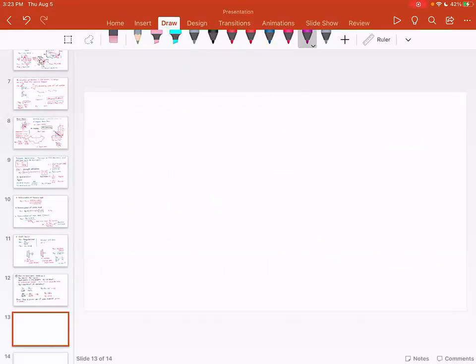So what we are going to do is find out the equivalent number of teeth for the pinion, and then find out the value of the Lewis form factor for the pinion. The equivalent number of teeth for the pinion is the diameter of the pinion divided by the module, divided by cosine of theta p, which is 80 divided by m.